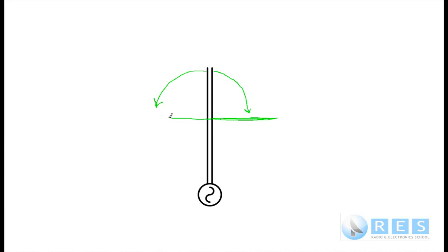We certainly have unbalanced this transmission line. It's a balanced transmission line and we've horribly unbalanced it. So there will be radiation now from these two wires which were once part of the transmission line. And if those two wires are a half wavelength long, that is called a dipole. And the impedance of a dipole at the feed point, that's this point there, is approximately 70 ohms. And you should remember that.